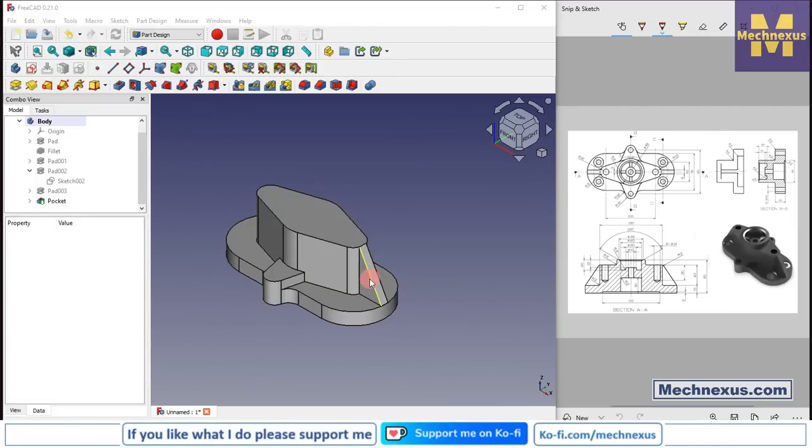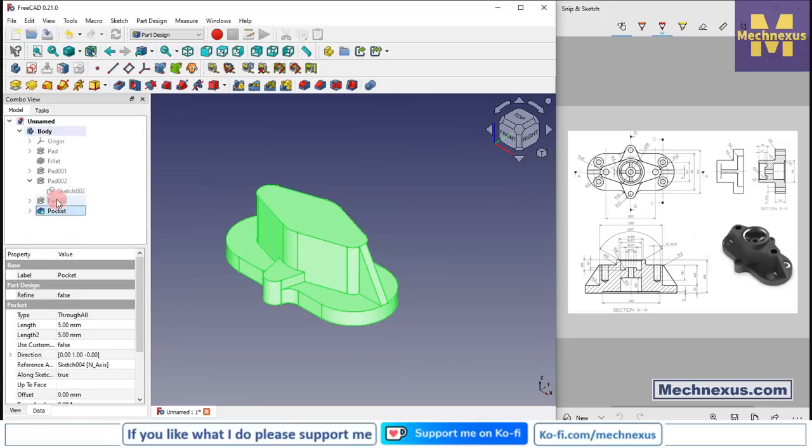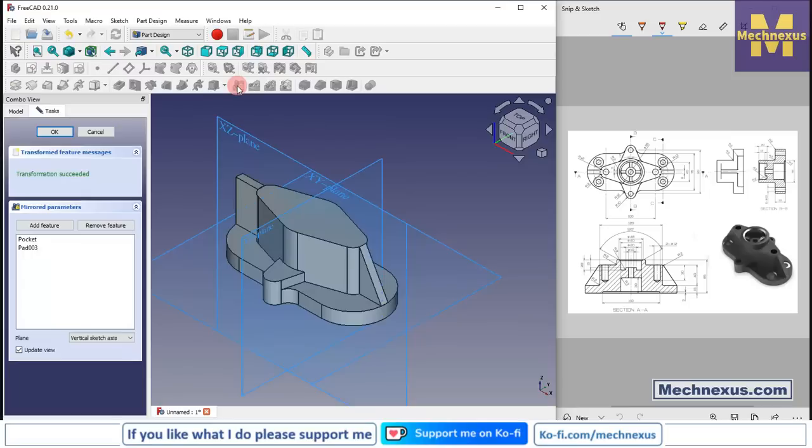Now we will mirror this rib on the other side. So we will select this pad 3 and pocket, and from here select the mirror. So you can see that pad and pocket is added, and here we will select the reference, and here